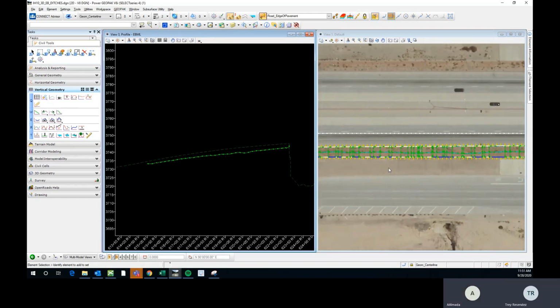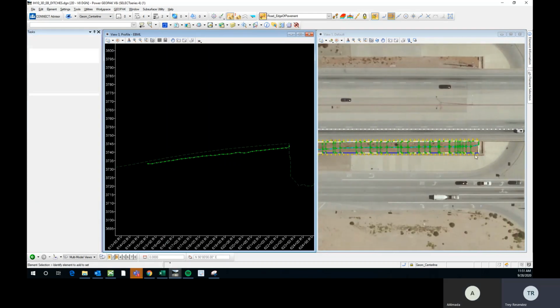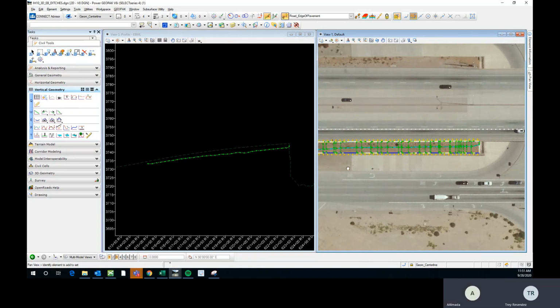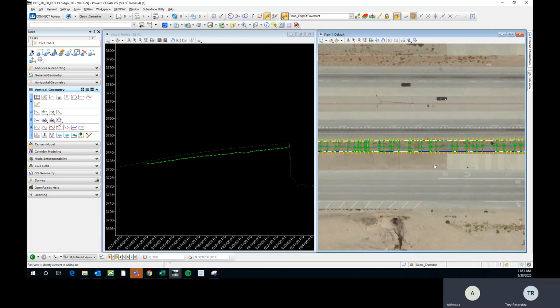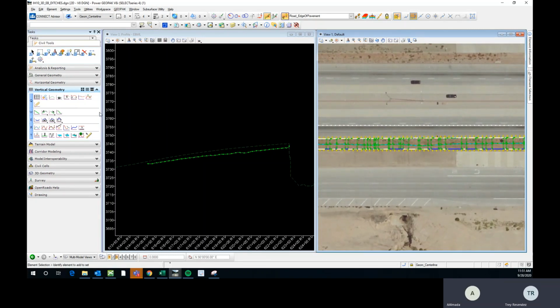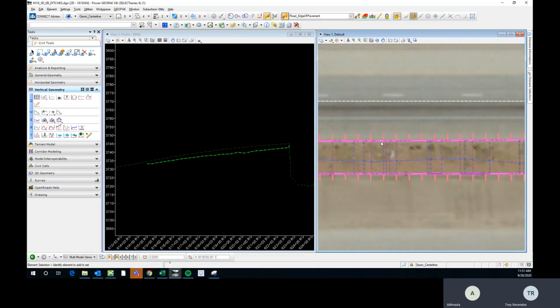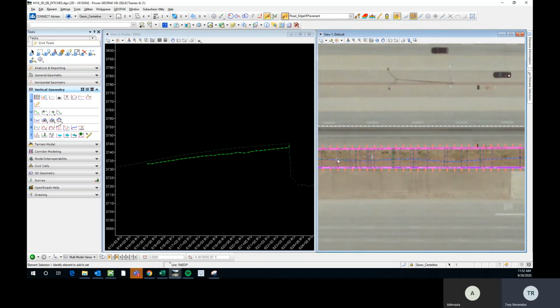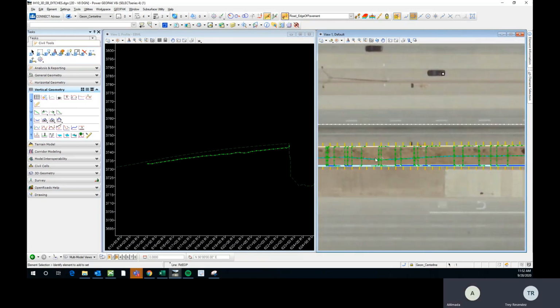And if you're going through this and it doesn't make sense for some reason, then just let me know and we can walk through it. So this profile that the program spit out, is that using your template, so using 4:1 or no? Yeah, it is. It's picking the 4:1 from this alignment vertically, and this other hinge. So it knows the horizontal distance between each line, and it knows the vertical difference. So it's able to solve this slope and find out where that would need to be.